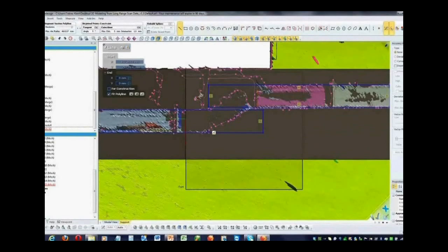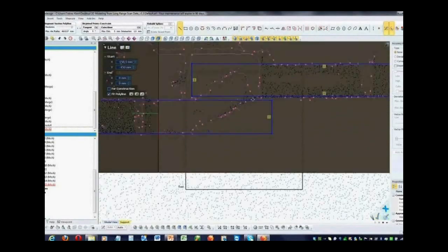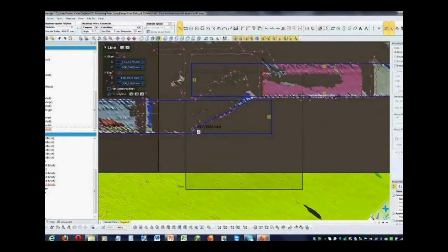Then let's look at this. Okay, here we have not very much scan data, but we can see there's a trend from here to here. And then I can measure the distance here. This is a redesign assistant actually, so it measures 296 point something, then we say 296 for example. And then I can define an offset from this into the other direction with 296 or probably 300. So I can make this the same distance.